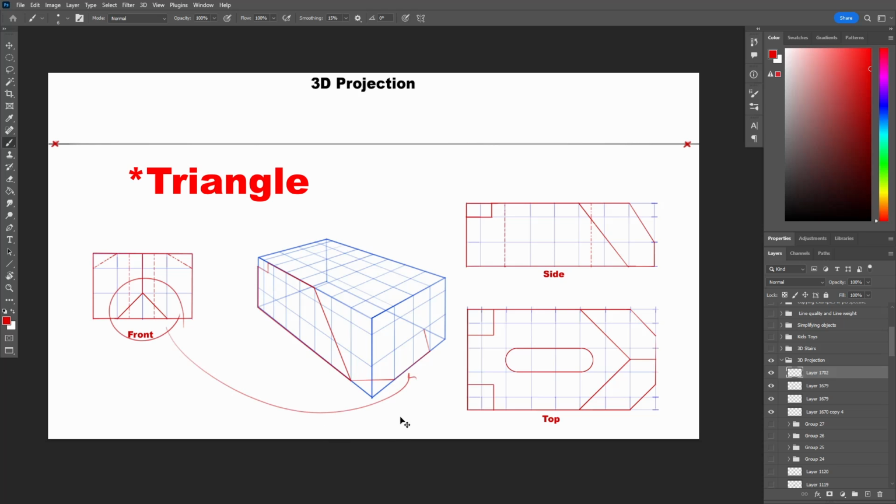So let's draw the rectangle next. Very straightforward, 1 unit high and 2 units wide. From a step, it will go as a slope to 1 unit in the top view, and from there it will go back to the side view. All this data is from the projection planes we are looking at. Every line I put down is from the information I'm reading in the planes.